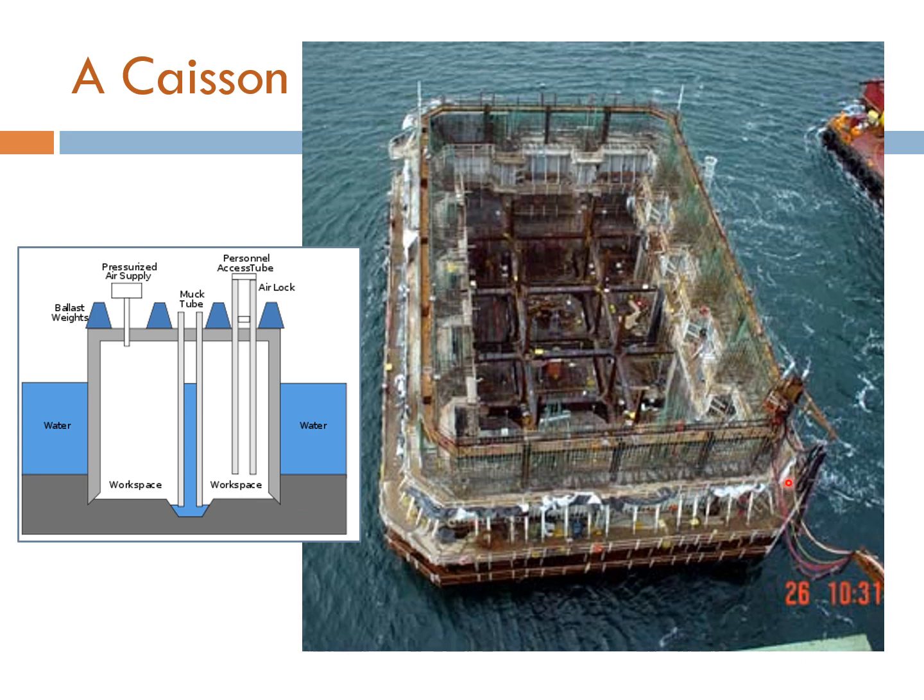As you can see in this picture, the caisson is typically large compared to the wave field around it, and notice that the wave can be reflected or diffracted by the structure itself, which is a behavior totally different from the cylindrical type structure where D/L is small.